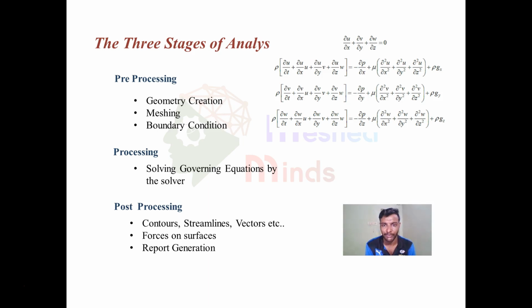For example, the governing equations that I have written here is for a fluid flow. So these are called Navier-Stokes equations, and this is the continuity equation, and these are the momentum equations. We'll be taking a detailed look at this if you're going to take the CFD module with us. But for the time being, we just need to understand that the solver actually solves such complex equations and then it gives out the results.